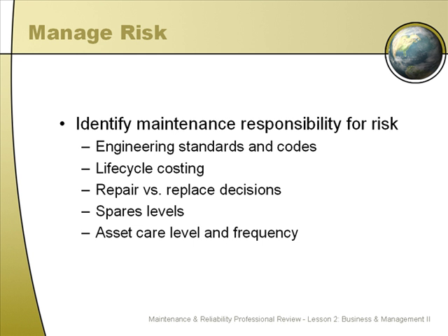Fifth, asset care level and frequency. Normally, the asset care level and frequency of doing things such as preventive maintenance were based on how long the machine could survive between failures. This is not necessarily the case when you're in a proactive maintenance situation. You're going to tune and refine the usage of many different tools, including preventive and predictive maintenance, and even run to failure in some situations where the piece of equipment is of low criticality.